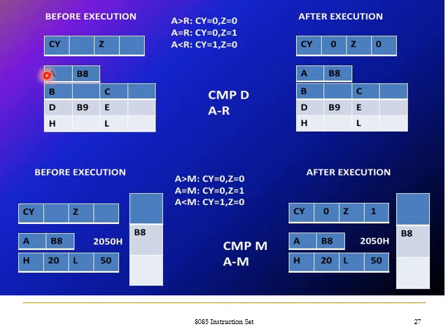Here the accumulator content is B8 and the D register content is B9. So B8 and B9 are subtracted if the instruction compare D is given. After subtraction, the result is not 0, so the zero flag is cleared, and we know that the accumulator value is smaller than the D register value. As it is smaller, no carry is set, so the carry is also 0, right?